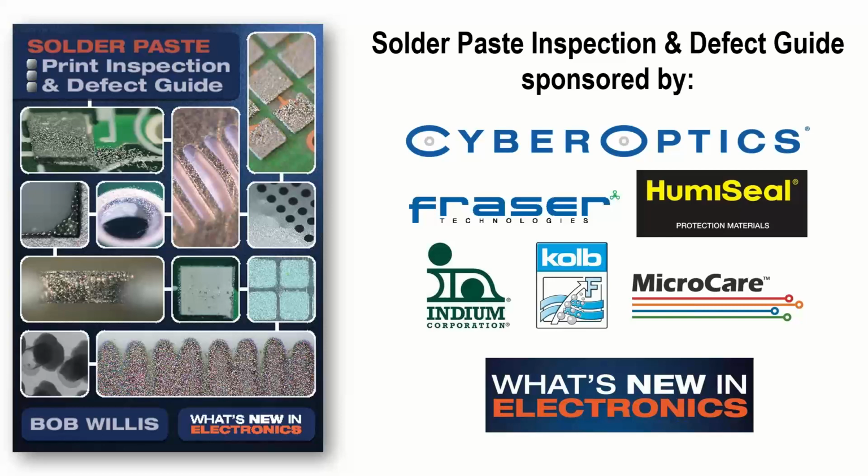In terms of a squeegee blade, again, that blade mustn't be damaged. If there's any kinks in it, breaks in it, splits in it, for any reason, then the problem you will get is a problem during printing, or you may damage the stencil. Some stencils have coatings on which actually allow the paste not to stick to the squeegee blade.